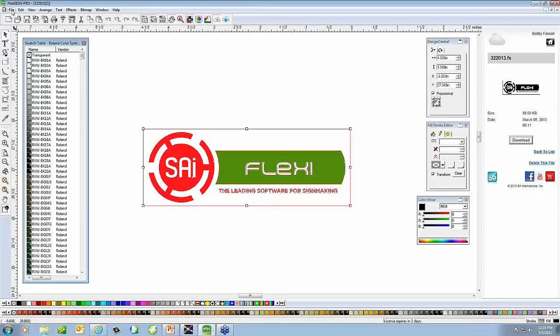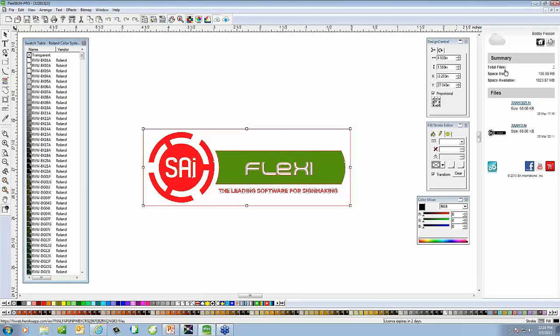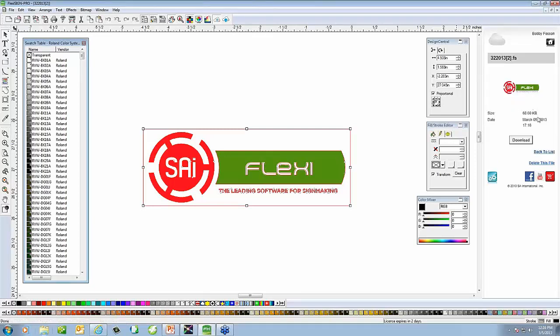We'll go ahead and I'm going to choose to go ahead and archive this file, which they have a small icon right up here at the top in Flexi Cloud that says Archive to Cloud. So I can click on this, and then at that point, it's automatically uploaded that file to where now I have both of them in here. See the black one that we originally started with, the color object that we have here. You can also manage these files simply by clicking on them. So if I don't need this anymore, I click delete. It's now off your server, and you've now opened up that file space for future use.